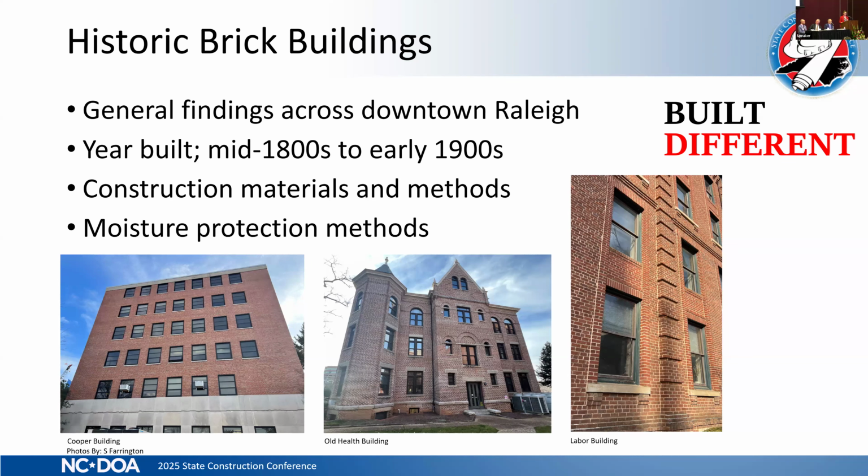The general construction of the exterior walls was designed to allow the water to flow away from the openings, and also to allow the moisture to be absorbed by the exterior brick and mortar. The openings are set back further to prevent water from flowing into the headers and down the jambs. Steep slope sills that are made of waterproof or water-resistant materials help to prevent water from flowing under the openings. And there are no weep holes or through-wall flashing in these buildings.